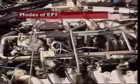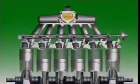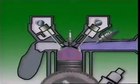This section examines modes of fuel injection for petrol engines. A mode of injection describes the timing and the sequence of injecting fuel. Simultaneous injection means every injector opens at the same time. Fuel sprays into each intake port where it stays until the inlet valve opens.